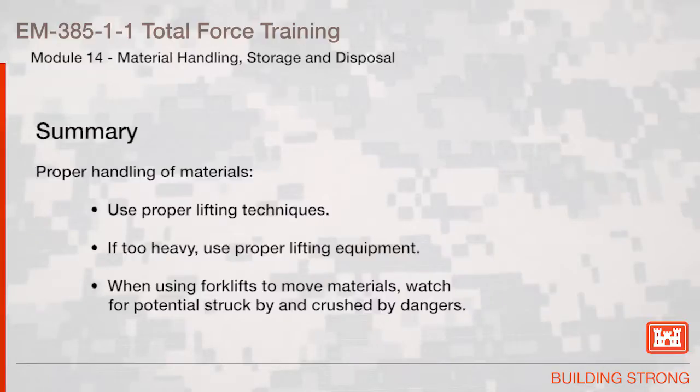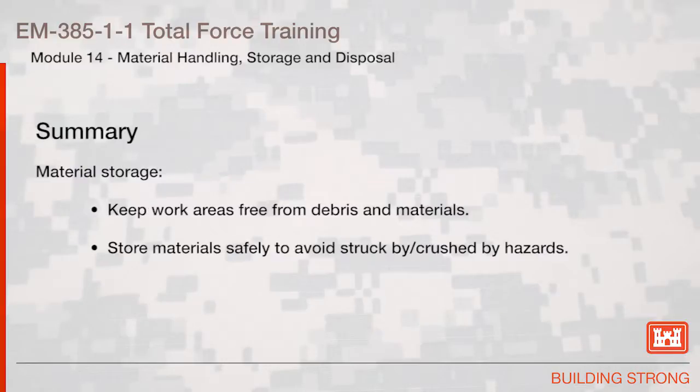For the proper handling of materials, use proper lifting techniques. If the object is too heavy, use proper lifting equipment. When using forklifts to move materials, watch for potential struck by and crushed by dangers. For material storage, keep work areas free from debris and materials. Store materials safely to avoid struck by or crushed by hazards.